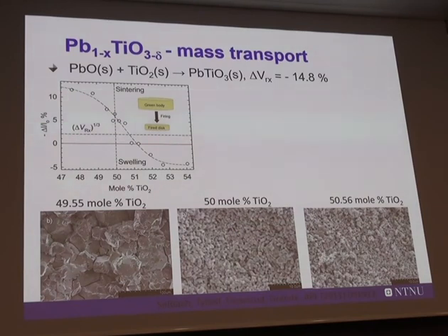In some materials, you use plasma or similar high energy methods to implement other types of defects. But normally you then quench the material to a very low temperature, so the quenched-in defects are stable. But if you want to have oxygen ion conductivity, you have to use the materials at elevated temperature, and you cannot trick nature. If you are able to make these kinds of artificial point defects, they will disappear. So the effect of the plasma will disappear.